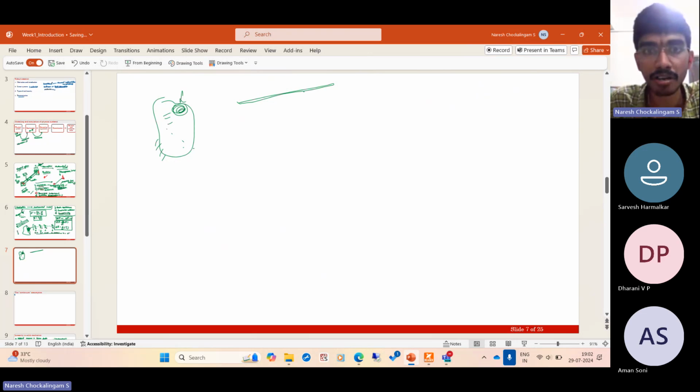But in 1D, what you can look at is very small segments of the member. Suppose you want the strain at this point P. Consider a small segment of that member, let us call its length X, containing the point, and see how much this length changes. Let it change by some delta X. Now take the ratio delta X by X.